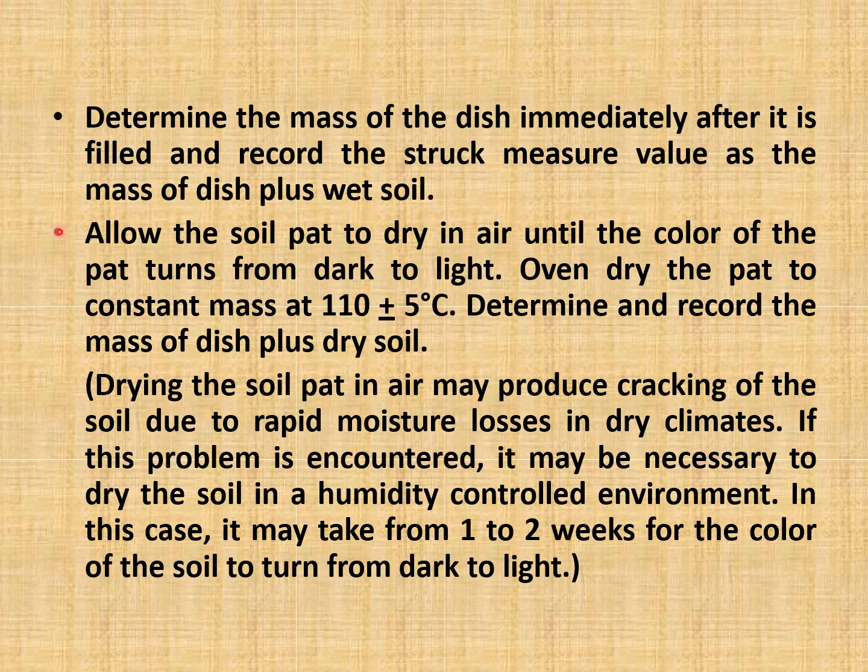Allow the soil pad to dry in air until the color of the pad turns from dark to light. Oven dry the pad to constant mass at 110 plus or minus 5 degrees Celsius. Determine and record the mass of dish plus dry soil.